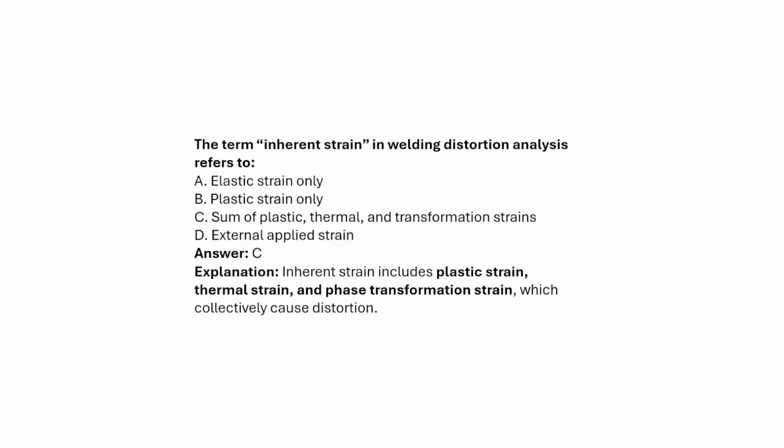Okay. The term inherent strain in welding distortion analysis refers to elastic strain only, plastic strain only, sum of the plastic, thermal and transformation strains, or external applied strains. Answer will be C. Inherent strain includes the plastic strain, thermal strains, and phase transformation strains, which collectively cause the distortion.